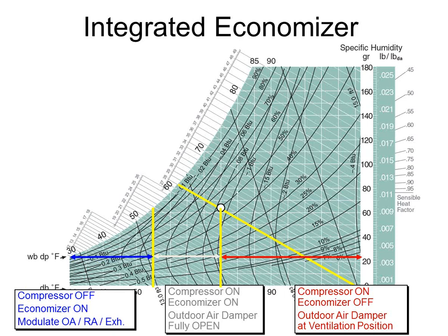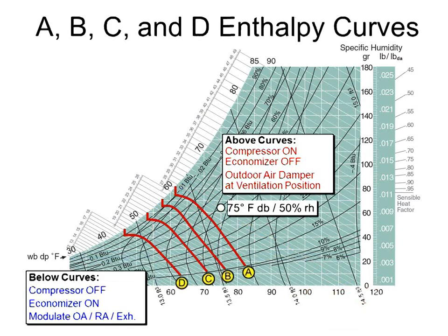If the thermostat calls for cooling and the economizer controller gets that signal, he says, you know what, yeah, I know you asked for cooling. It's not really a nice day outside. It's like 92 and nasty, so I'm just going to not open the damper, and I'm going to go right to the compressor right now on stage 1. Right, that's basically how that guy works.